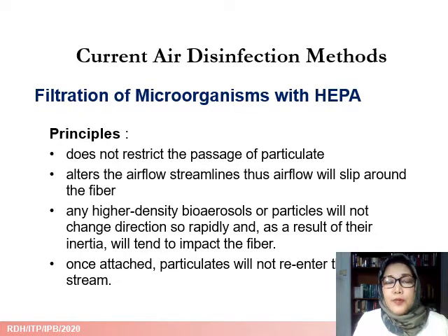Here are the principles of filtration of microorganisms using HEPA filter. The filter does not restrict the passage of particulate. Instead, it alters the airflow streamlines, thus airflow will slip around the fiber. Any higher density bioaerosol or particles will not change direction so rapidly, and as a result of their inertia, they will tend to impact the fiber. Once they are attached to fiber, the particulate will not re-enter the airstream.